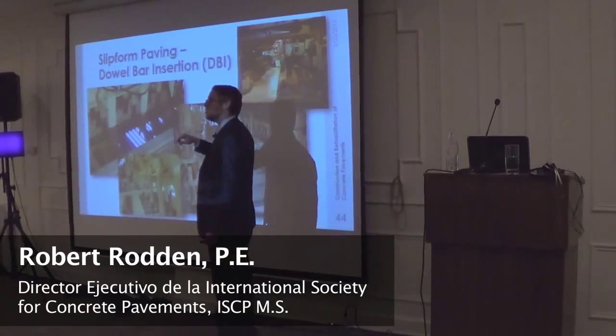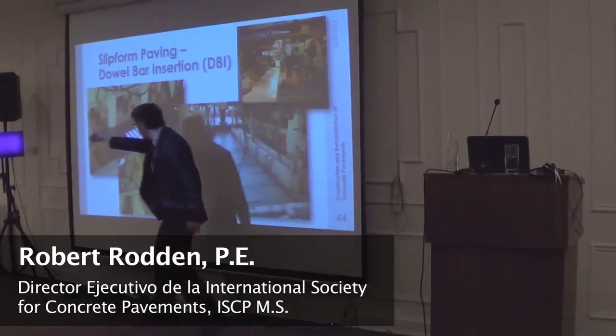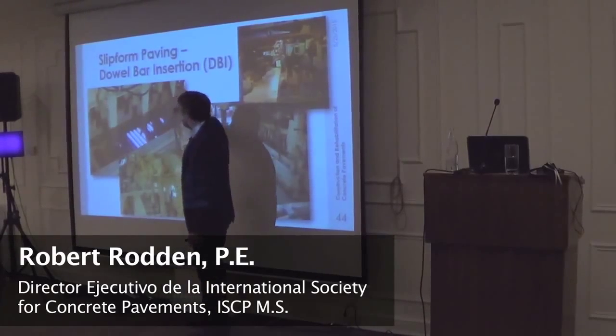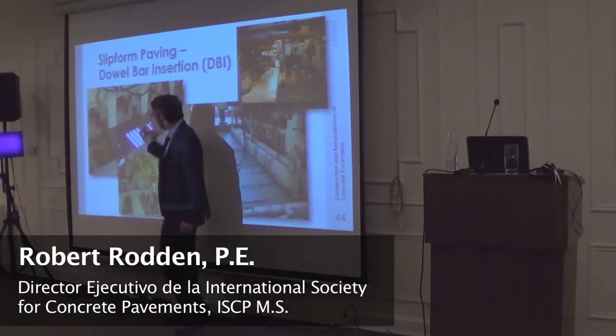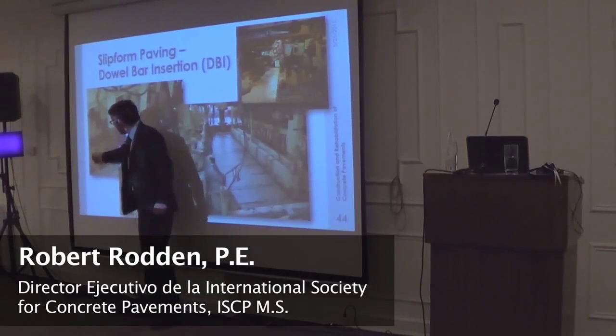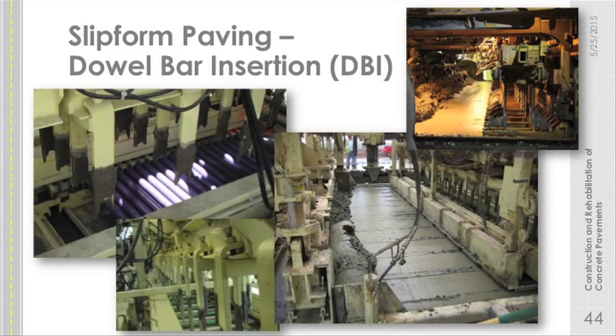Those bundles of dowels get cut. And there's a cartridge system that feeds them through. And when one of these passes by, a hole like this, it just drops in. So at that point, there's a dowel sitting in a hole. We then have this I-beam. It's a vibrating beam across the top. You can see part of it there. You can kind of see it here.